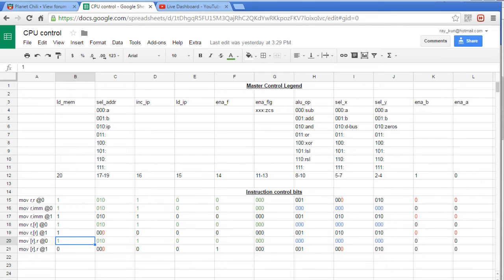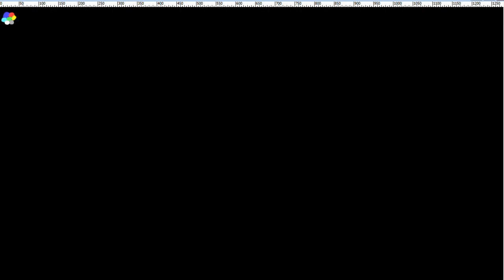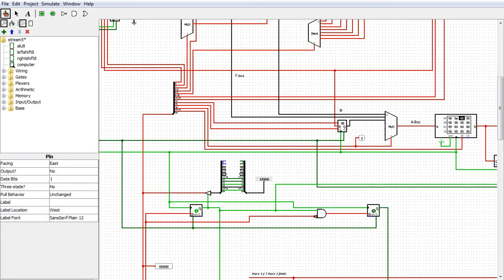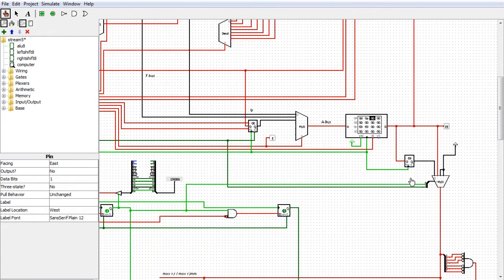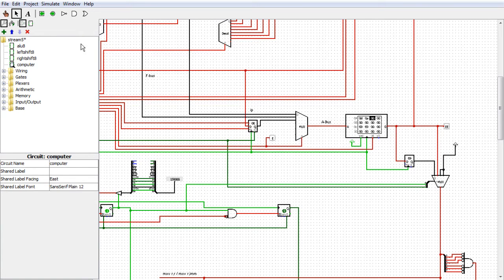So what I did was, when I first came across this problem, wait, why did I bring that up? Here we go. I thought about it, and I figured there's got to be a way to make this work. Obviously the simple way to do things is to simply connect this to the latch, and then have the latch directly drive these lines here. So don't go through the multiplexer. But the multiplexer's job is to give us access to the opcode in phase 0.